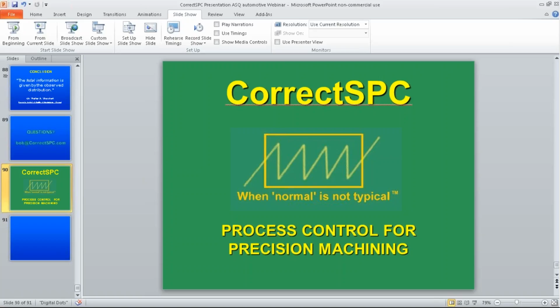things getting worse from this charting methodology, and the engineers in my plant are tickled to death because they can see this now where they weren't able to before. They can see that suddenly a particular machine has much more roundness than the similar machines. So, well, how is this happening? Then that's when they find out that they have problems with their chucking, they have problems with their bearings, or whatever type of repairs need to be made.